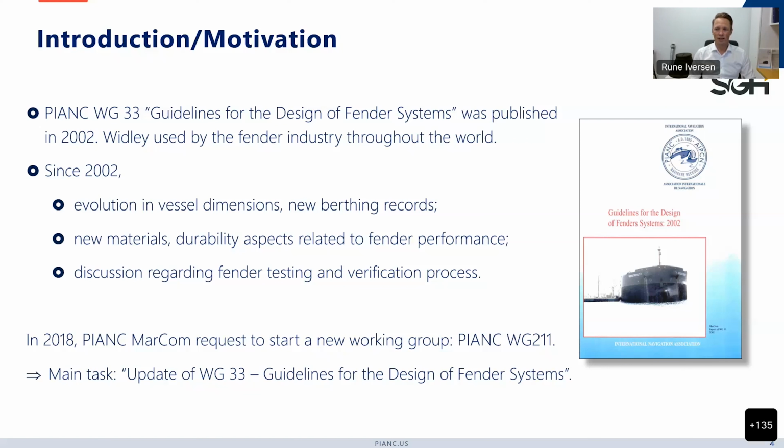Since 2002, there has been a lot of evolution in vessel dimensions. There's been a lot of new work done on collecting data on actual berthings, velocities, angles, how do things actually happen. We're dealing with new materials, new studies that have been done on durability aspects related to fender performance. There's also been discussions regarding specific fender testing and the verification process of this testing.